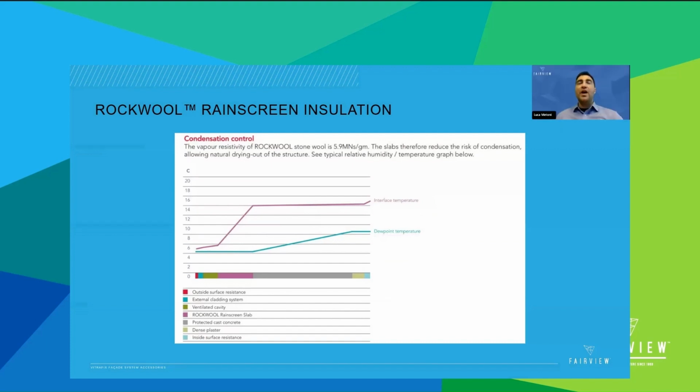How the insulation could help in the moisture management condensation. So what happens is that whenever you have a cold wall, the moisture that is traveling within the wall could reach the dew temperature. So if the wall is too cold, the moisture inside could condensate, creating a buildup. If you add the insulation to the cavity, then you create a warmer wall, you increase the dew point, which means the interstitial condensation risk inside the wall will be avoided. There will be no moisture buildup and no risk of mold trapped in the wall layers.